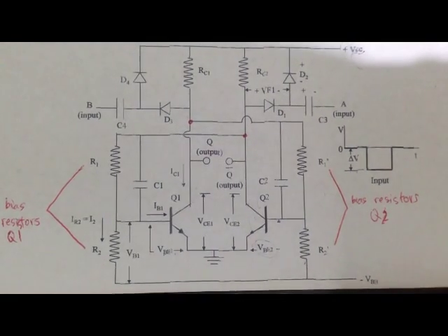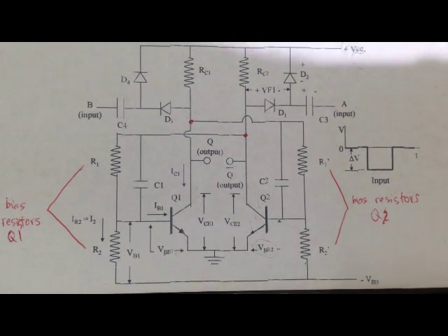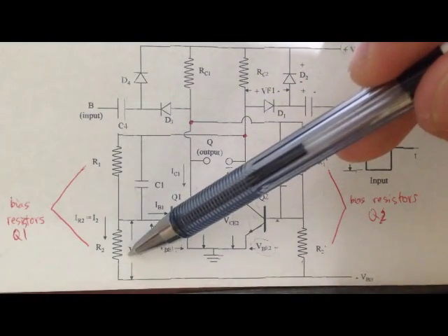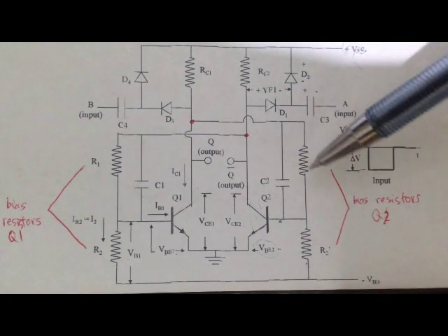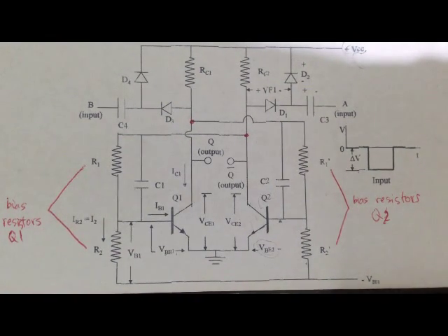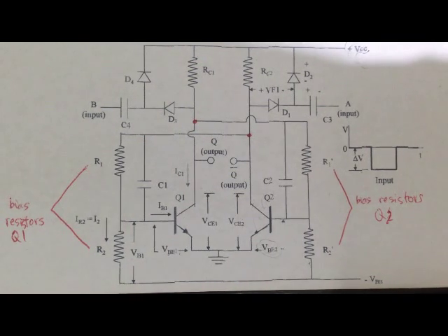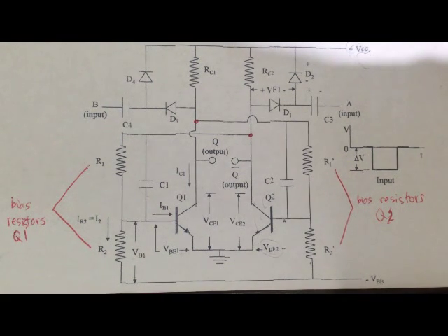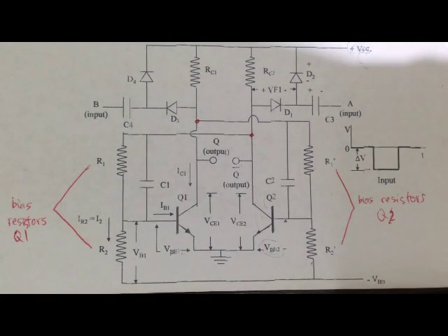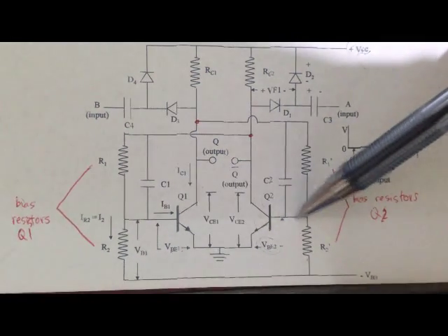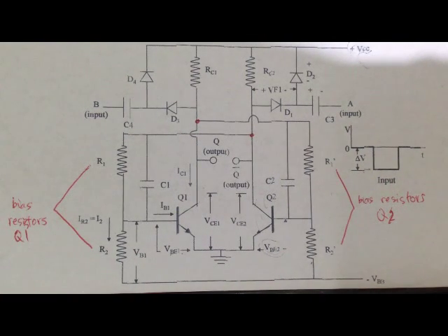In designing a bistable multivibrator, you may start from specifying the supply voltages and collector resistors. It may also start by specifying collector current. R1 and R2 must be made as low as possible to provide stable bias level, yet large enough that they do not overload RC. Same applies on the other side. The rule of thumb that bias current passing through R2 is approximately equal to 0.1 IC can be applied. When the value of RC is computed, the next larger standard resistance should be selected to ensure sufficient voltage drop along RC to keep the transistor in saturation. The bias resistances R1 and R2 should be selected as the next standard size smaller than calculated so that more base current than required for saturation can be obtained.